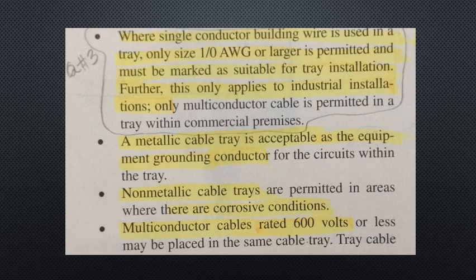There are many specific rules regarding the types of wire and cable that can be used in a tray system and how those wires and cables must be arranged within the tray. Article 392 of the Code permits trays to be used as a support system for wiring methods that can be used without a tray. Uses permitted and not permitted are as follows.